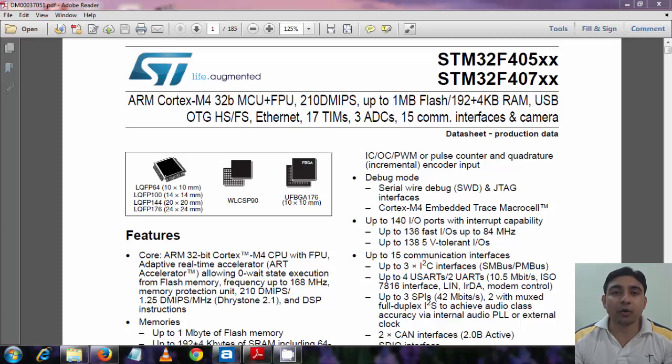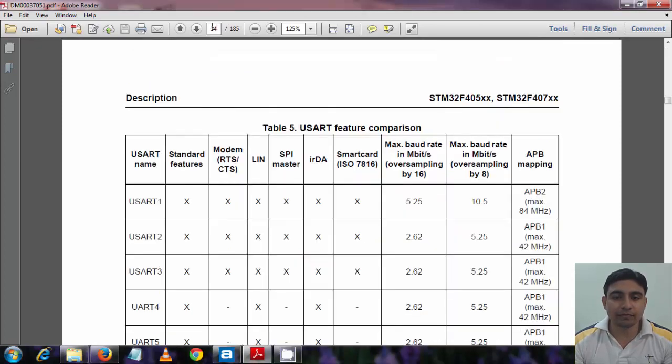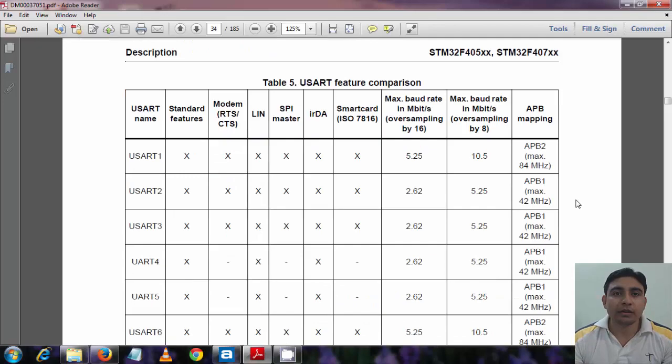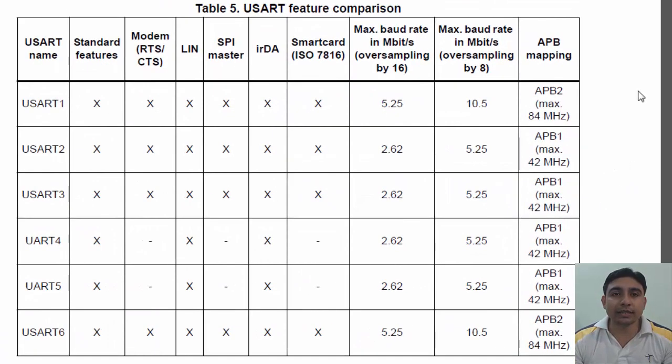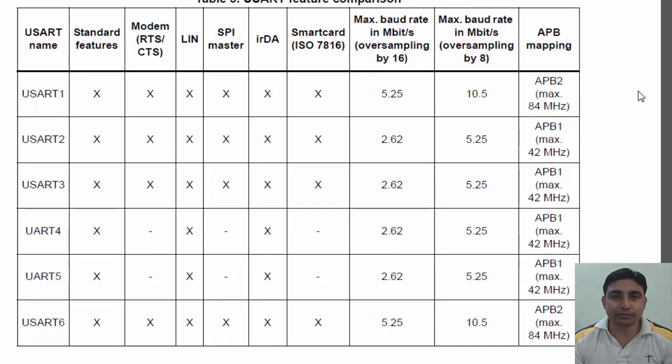So here I have opened the technical data sheet of the microcontroller present on the STM32F4 discovery board. Now let's go to page number 34. Okay, here you can see that we have a table. If you look at the left side here, we have USART names written one by one.